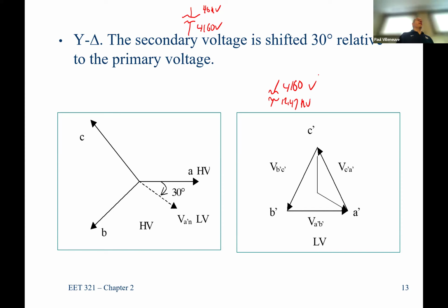So why is there a phase difference? Because to get to 12.47, there was another transformer that went from 46 kV to 12.47. And that was probably delta Y, introducing a 30-degree phase shift. So when I mentioned the top of campus can't connect to the bottom of campus, the reason is because there's a 30-degree phase shift, and there's no way to get rid of that.